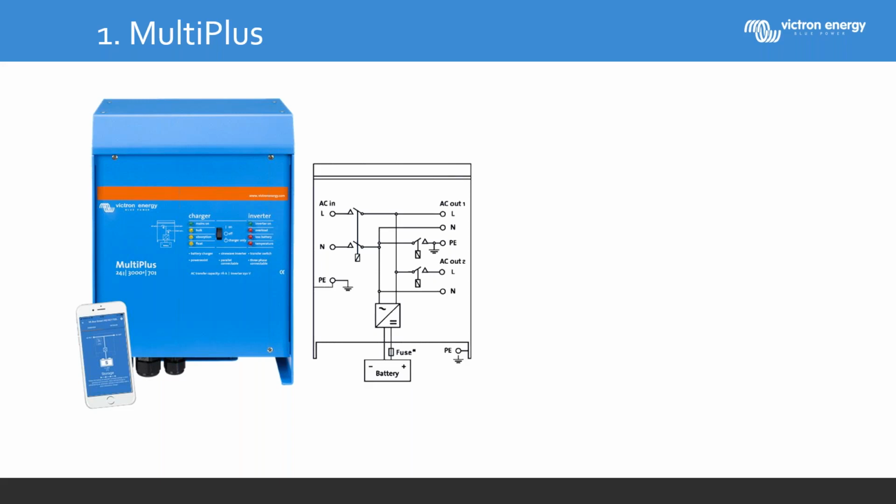So this relay will be linked to the AC input relay. There's always a 3-minute delay for this one to close after the AC input is closed. So, for instance, the generator is connected. After 3 minutes, a timer will close this relay. You are also able to program the inverter to operate this relay under different circumstances. So take it out of default mode. Sometimes if you want to do load disconnecting, there are various parameters for that.